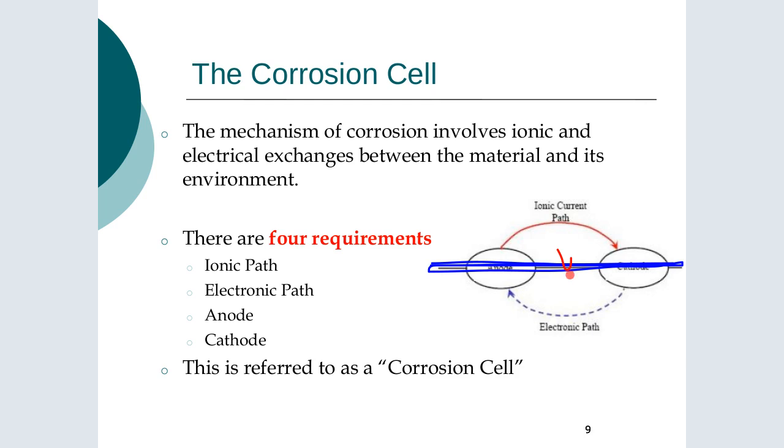Another feature that may occur with damage is crevice corrosion, and we'll mention this briefly as we move through the slides. In crevice corrosion and pitting corrosion, you have a change locally in the environment where corrosion is occurring, and you get a very high rate of attack because you have a much more aggressive environment. It's a microclimate that is established inside a confined region.